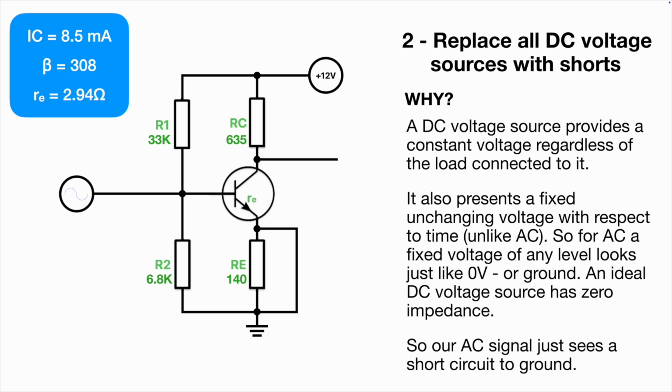Think of a sine wave. The sine wave goes through its positive excursion, it reaches its crest and it dives back down, it crosses the line, goes through its negative excursion, reaches its lower crest, and then it goes back up again. And actually, it doesn't really affect the character of the AC waveform at all. All you're doing is raising it up or lowering it down a bit, but the waveform is what it was before. So it makes no difference whether the bias level is at 12 volts or 6 volts or 0 volts, it might as well be at ground. And that is what we do.